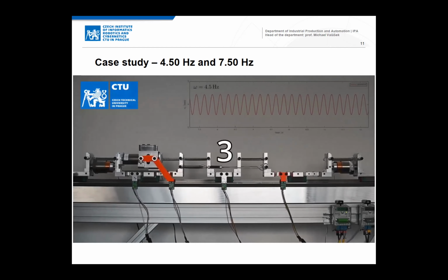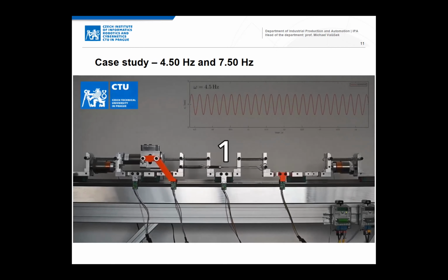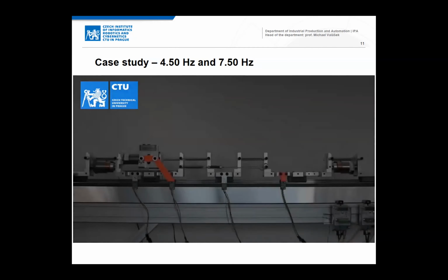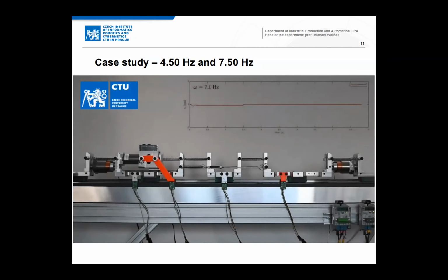The voice coil on the right is used to mimic the disturbance. Now, this voice coil is used for the delayed resonator to stop the vibrations, and as we can see, the cart in the middle stops vibrating. The voice coil on the left is used for the additional stabilization controller, which was in use in that case.